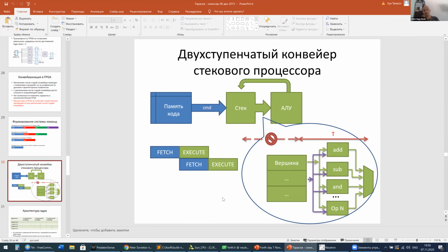It is possible, but from our experience, the clock speed of that CPU is slightly lower, because we need to fetch operands from the register file using several fields of our command, because our command will contain information about exactly which registers will be operands for the next command.